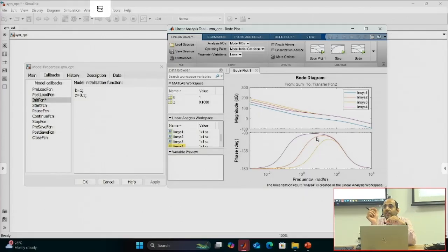Then by playing with k, once you have finalized z as per your stability requirements, you say, I want this much phase margin, you get z, and calculate the frequency at which the maximum phase occurs. Now that is fixed. The only objective left is to align the gain crossover frequency with the frequency where the maximum phase occurs. For that you can just change the gain and move it left or right, wherever, so that you align with it. So this is what I conclude in this session.